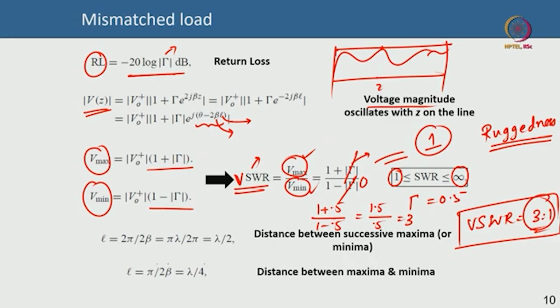Typically bipolar devices are tested in this kind of thing, because bipolar devices cannot go to very high voltage standing wave ratio. Many transistors such as LDMOS and gallium nitride HEMTs can actually go to much higher. People have even tested to 10:1. 10:1 would be crazy, right?